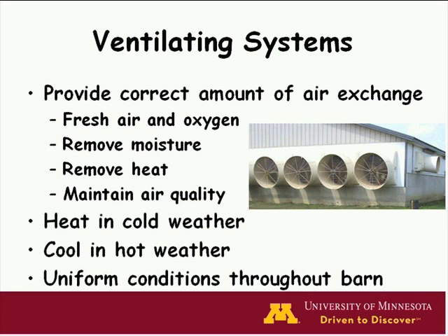In the hot weather, we will use a ventilating system to cool, and we may include an evaporative cooling system. And we expect this system to operate year-round and maintain uniform conditions throughout the barn. Proper heater management and thermostatic settings are needed to make sure that all of this heating and cooling is done in an efficient manner.